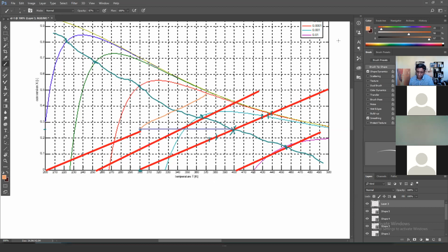Okay, thanks. So we've gone from the CSTR, which we know is a nice high rate region. That was our criterion. Then we cooled back to 300 Kelvin, and then we are now considering a PFR. Again, we know the PFR is adiabatically operated, and so we'll be moving along. This line is intended to be parallel to the red line because it's the same gradient, the same adiabat.